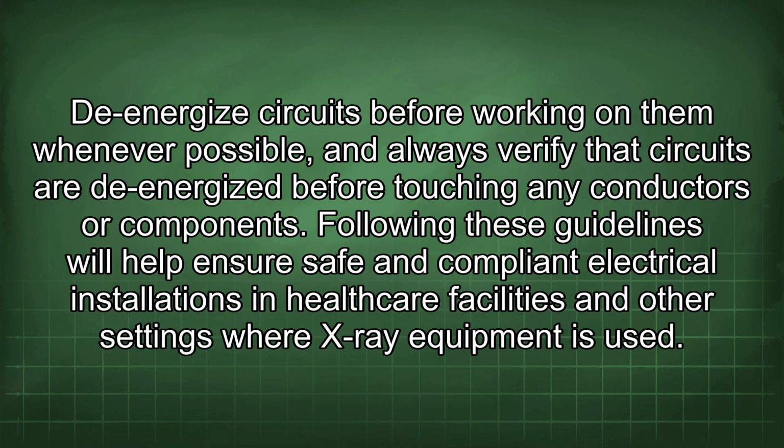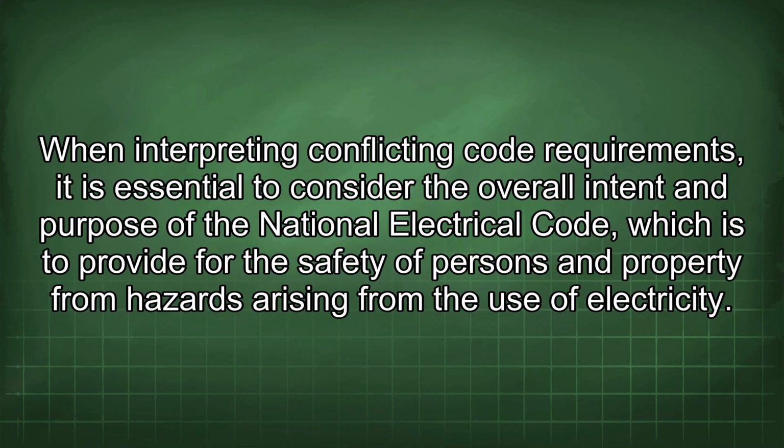De-energize circuits before working on them whenever possible, and always verify that circuits are de-energized before touching any conductors or components. Following these guidelines will help ensure safe and compliant electrical installations in healthcare facilities and other settings where X-ray equipment is used.